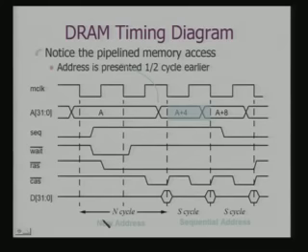This is precisely the reason why the ARM processor core provided SEQ as an output signal. But you can understand that to use these signals for actual interfacing, you need to implement the interfacing logic.